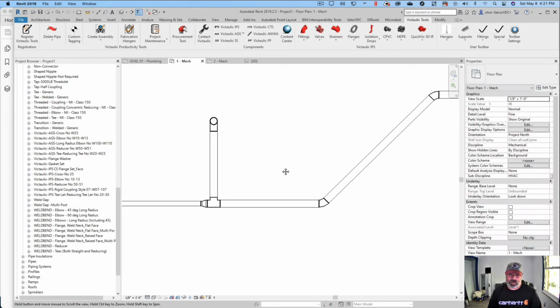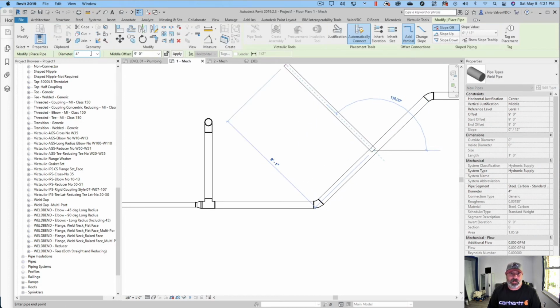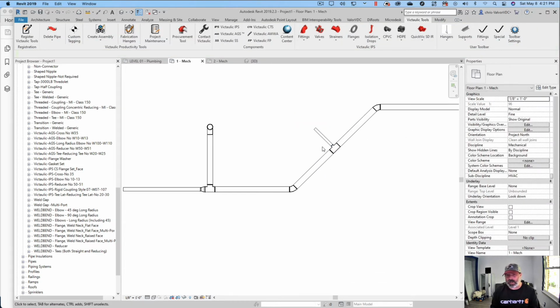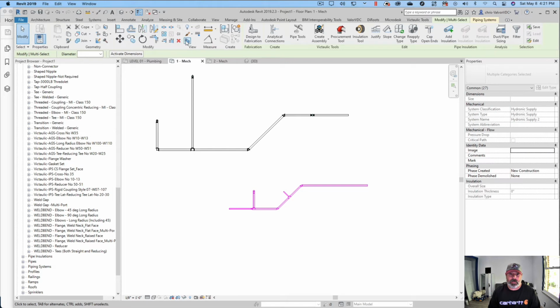One of the things you can also do is with these, you can come off the pipe at an angle. You can reduce the size. So let's say 2.5 inch, because that's the smallest one you got. If you're gonna, whoops, okay. So it's all the same size. So that's pretty much how you set it up and you route with these fittings. You want to see it in a 3D view, come here.